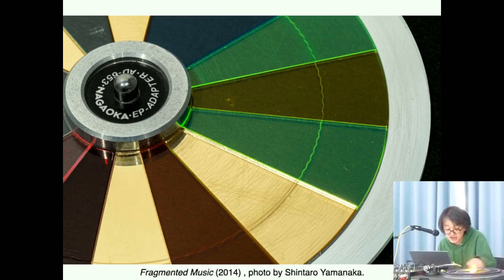Here, each color corresponds to a specific number of zigzags, which means the frequencies, ranging approximately from 60 to 120 Hertz at 33 RPM. Gold segments represent silence with smooth curved lines, and a silver outer ring prevents centrifugal scattering. The endpoints of each group of arcs are centered for connectivity. And to prevent needle skipping between arcs, we changed the focus of the laser cutter to widen the width of the groove.